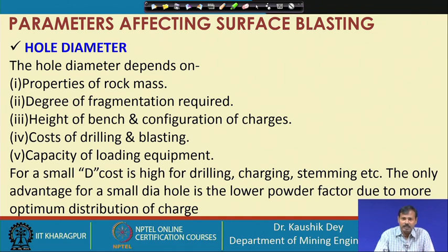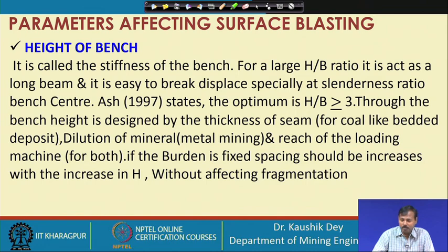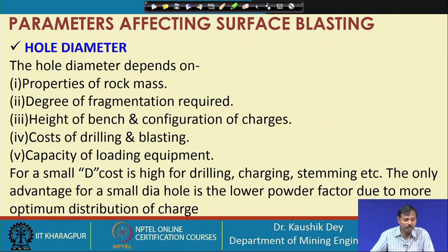Instead of this, if you are having a large diameter hole, then you can have a large burden and large spacing. That means the desired fragment size will be of a larger size, and you should have large loading equipment which can handle that large size, but the production target that can be addressed is very high.